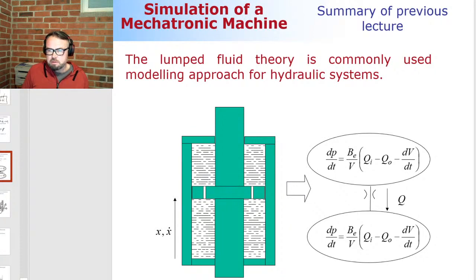So we looked at the simple fluid damper, and we concluded that the damper can be modeled in such a way that we can compute the pressure here in this side of the piston. This is the same volume. And now what I mean about dividing the hydraulic circuit into volumes where the pressure is assumed to be equally distributed. It means that this area can be considered as one volume, meaning that the pressure in this corner is exactly the same as the pressure in this corner. And that is the case.